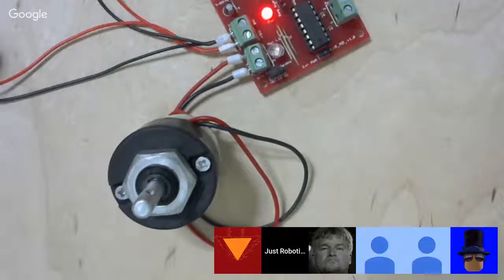It works exactly like how we use digital write, but instead of using digital write, we will use analog write. Okay, and instead of telling high or low, we give a particular value that says what has to be done. I mean, what should be the value? Because when I say 0, it is off, low, and when I say 1, it's high or on. So anywhere between 0 to 256, or rather, when I say 0, I'm actually reducing 1 value, which means it will be 0 to 255. Anywhere between 0 to 255 will make my system go on and off. Okay, now let's take a simple program.